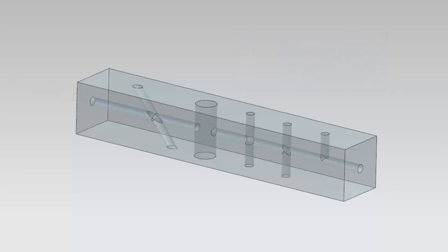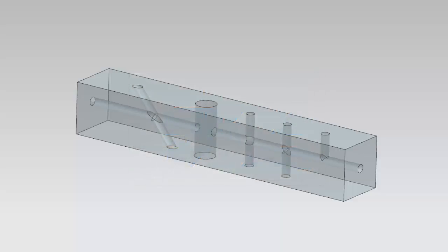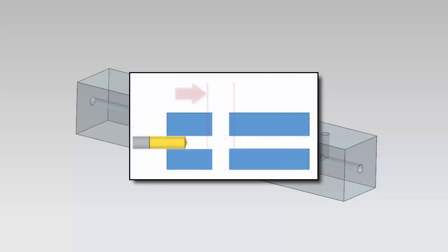Sequential and deep drilling operations identify intersecting holes and apply cutting and non-cutting feed rates to each drill cycle. If the intersection is greater than or equal to the specified crossover distance, NX crosses the intersection with 3 motions using last cut, crossover, and first cut feed rates. If the intersection is less than the specified crossover distance, NX crosses the intersection at the stepover feed rate with a single motion.